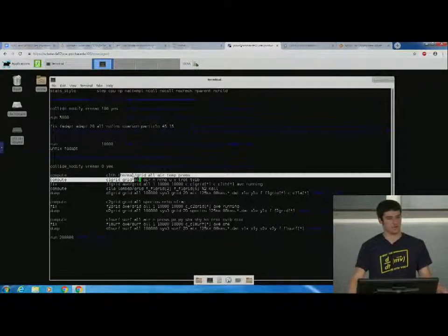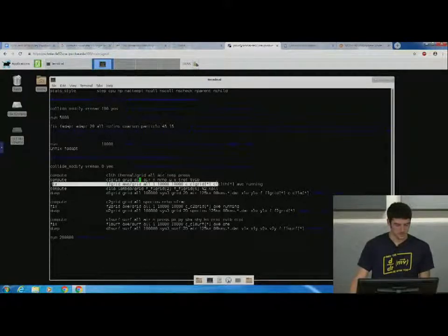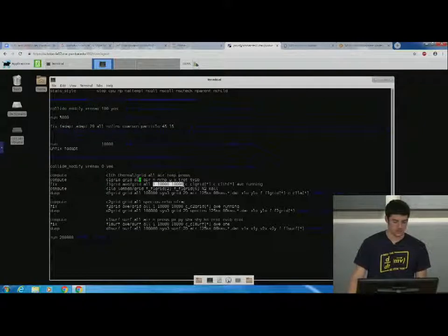Next, here we just computed, and we're computing every time step. So we're not really getting a good set of properties because things obviously vary greatly from one time step to another. So what you want to do is average over a greater number of time steps, which is this fix command. So this fix will average our computes, and these three numbers are a bit confusing. This is saying I'm going to perform the averaging over this many steps, 10,000 steps. Then here it's going to be the last number of steps within that first. So basically the last 10,000 steps within every 10,000 steps. And this is how often I'm repeating it.